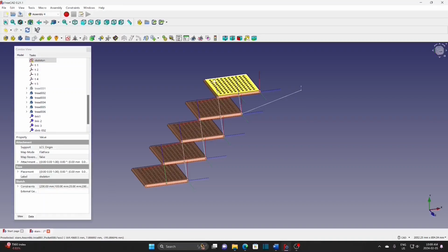For the length, the Z-axis is vertical and X is horizontal. So the LCS at the length needs to match the LCS on the sketch.